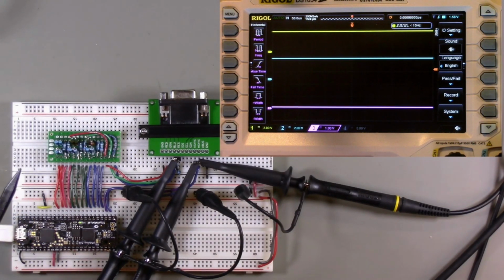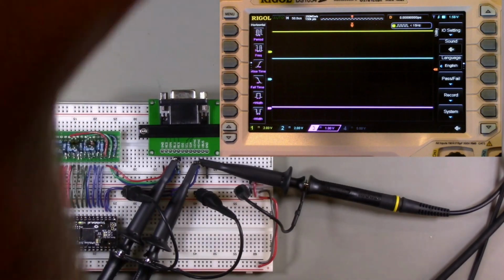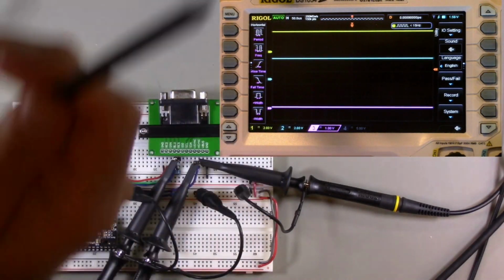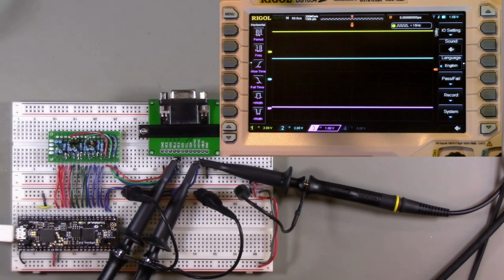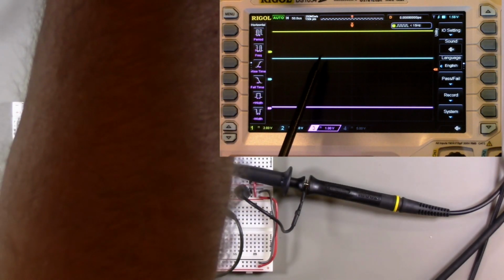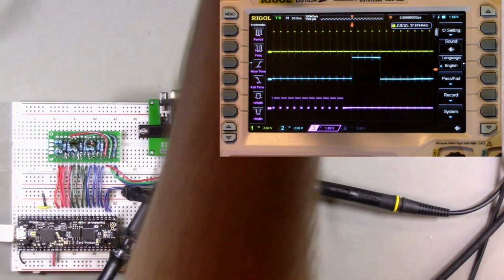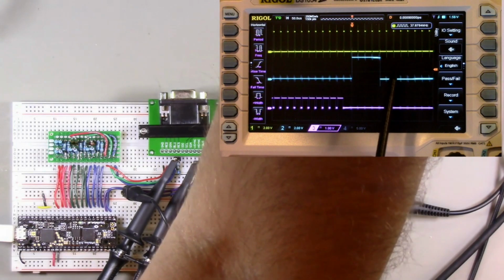Alright, so what I'm going to do is show the H-sync and V-sync and the blue color voltages on the oscilloscope, and the triggering is set so that we trigger on the vertical sync, and essentially we'll see the horizontal sync and the color signal relative to the vertical sync. Alright, so let me upload the design into the FPGA. Okay, so here we go. So here we can see a vertical sync pulse.